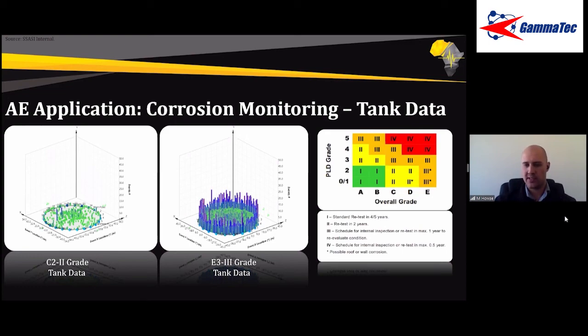We have a question here for different sensor types for vessel thicknesses. In general, no. And this is because we're not inputting signals. So it's not like UT where you need a lower frequency sensor to get more penetration. In acoustic emission, we're more worried about the damage mechanism that we're looking for and what frequency range that falls in. So if you have a very thick vessel, or say your areas of interest are further away, we might use more sensors in a denser array rather than changing the type of sensor.